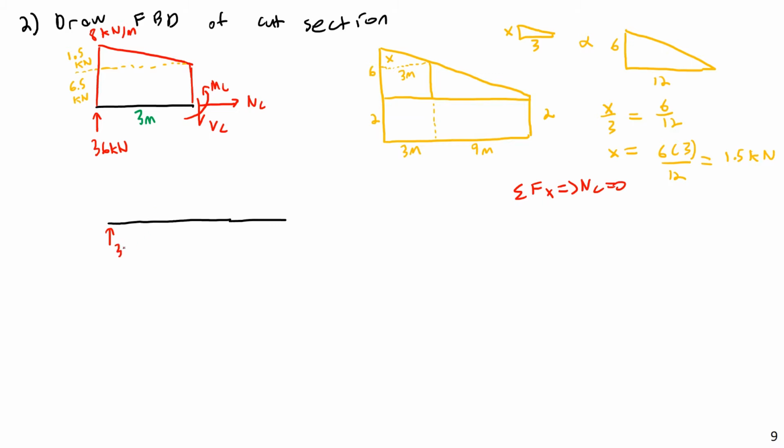I have a 36 kilonewton reaction force at point A. Then I have a downward VC and some, again, counterclockwise but positive because of where it is on the beam, internal force MC. Now I'm going to have two equivalent point loads. The first is going to be from the triangular portion. And I know that it's going to be 1/3 the length of the triangle, or simply 1 meter from the left-hand side.